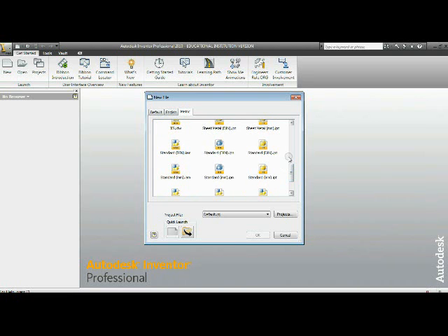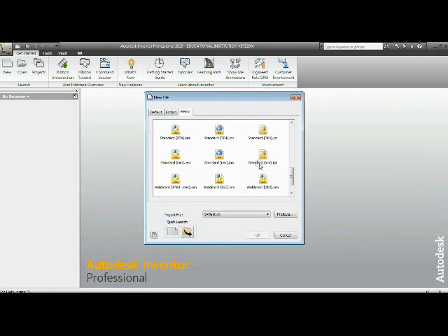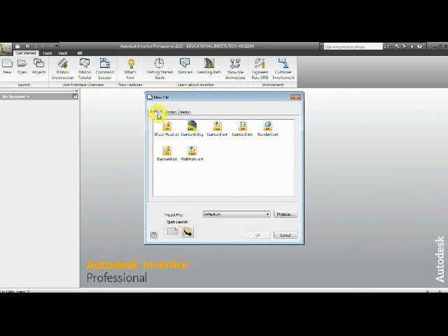Now, since we're going to be dealing with parametric solids, what we're going to be looking at is .ipt files. So we'll look at the standard millimeter IPT, or Inventor part file, if we're in metric. Now again, we'll go with the default and we'll use the standard .ipt.